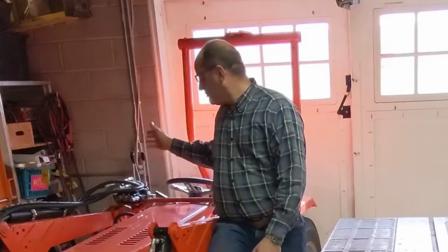So here I was driving along with this spinning hydraulic motor, and I pull that lever and I cut off all the fluid flow into the motor. The inertia of the machine keeps the rotation going into the motor, and that produces pressure, and that pressure has no place to go. So it increased the pressure in that line, and the line blew. Something had to give, and the poorly done flare fitting turned out to be the weakest link.